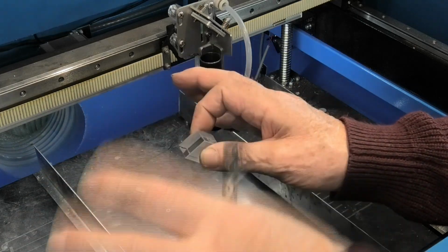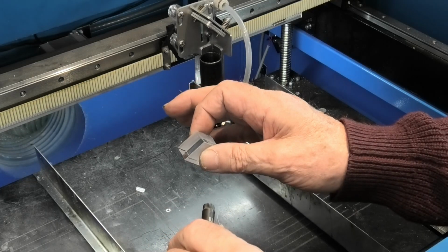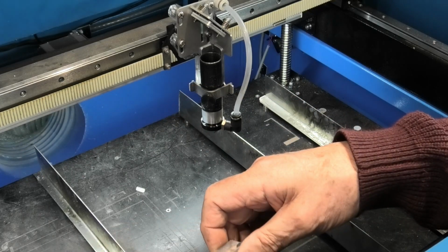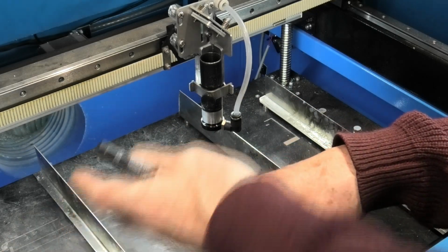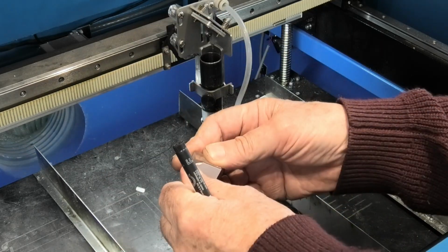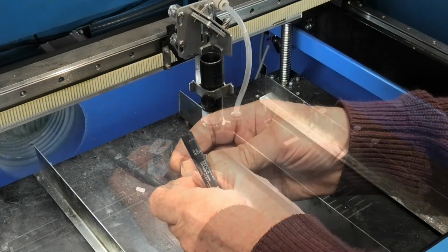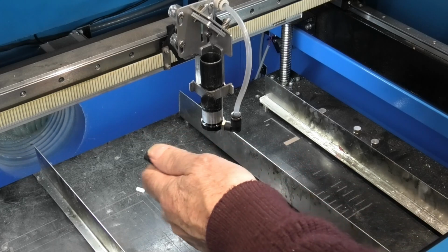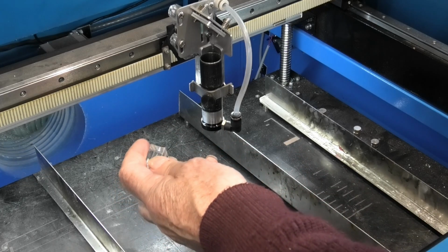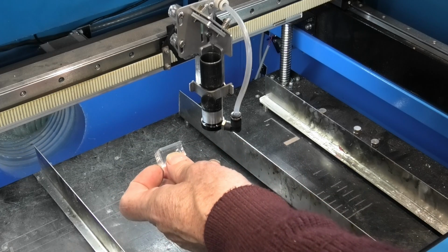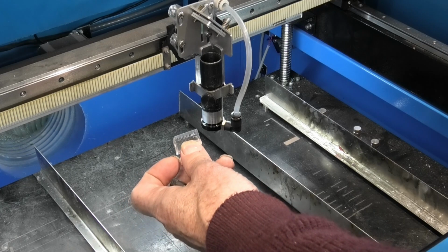And the third option is the RF machine, which is only half the power of this. It's only 30 watts. This is a 70-watt tube. The laser beam itself is a fascinating thing. So how did that 25mm focal length lens manage to cut a virtually parallel cut through 15mm thick acrylic?